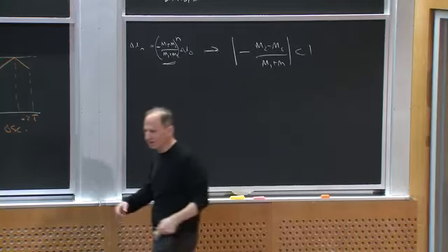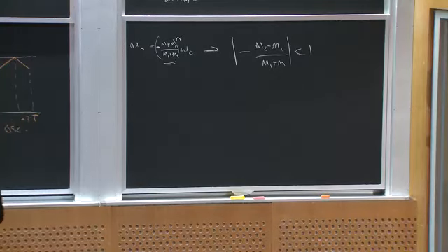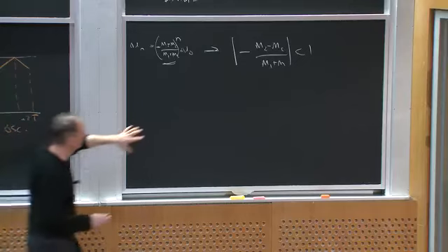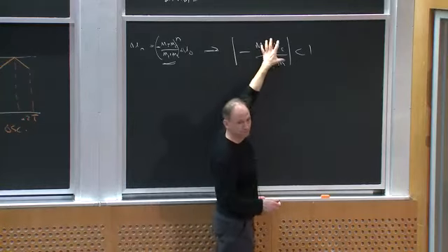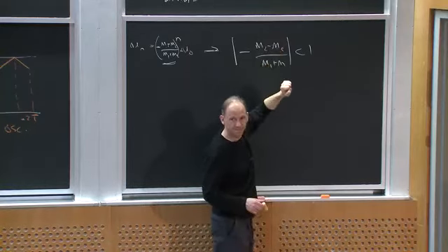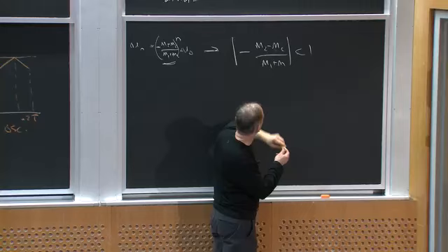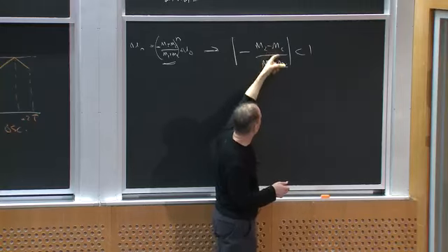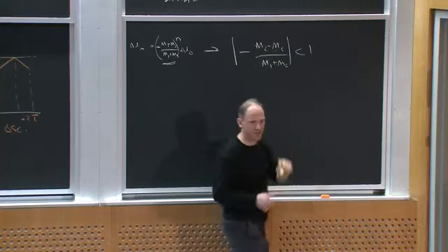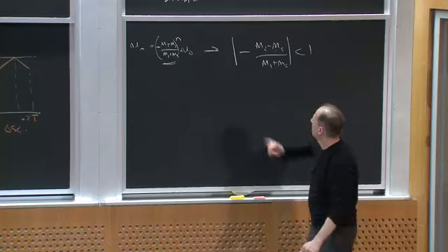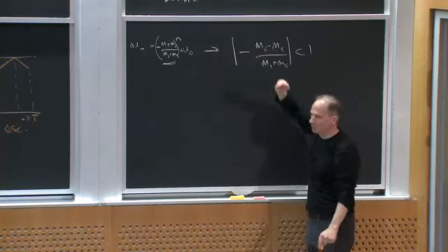I've got a discrete time model, and it's going to decay if this term is less than 1. What that says is that if I make MC bigger, the numerator gets smaller and the denominator gets bigger, so a bigger MC will make this decay more quickly. In fact, if I made MC exactly equal to M2, it would be gone in one cycle.